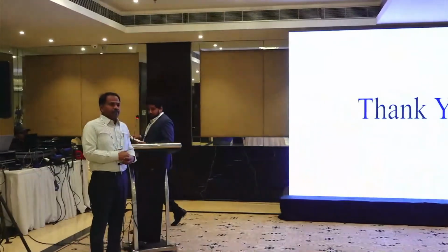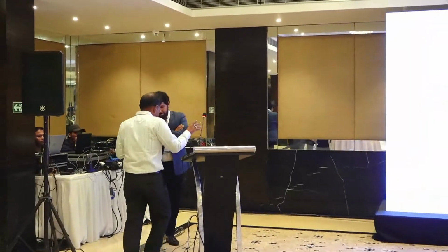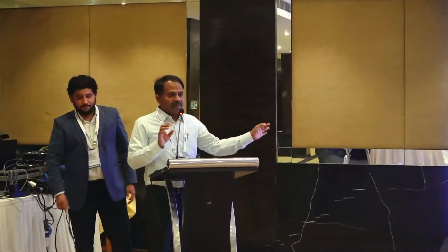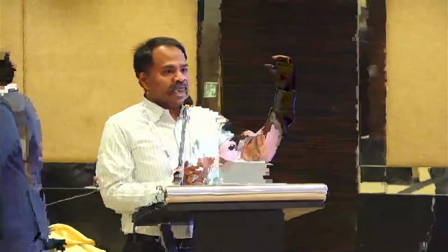Are you doing the NDT tests as an experiment in the laboratory, or can you do it on live structures? Sir, this is a part of the study which you have done. This will be conducted on the live structures only. Yes, sir. In existing in-service structures of 25 years, 30 years, we measure the pre-stress loss of 40%, 50%, 60%. So this technique will be directly adopted at the site to measure the stress in the pre-stress. But once you do that NDT, that will not be useful, no? That structure will get damaged.